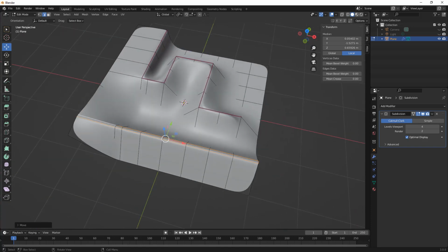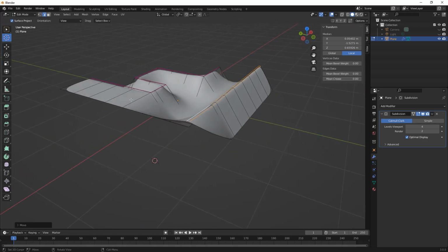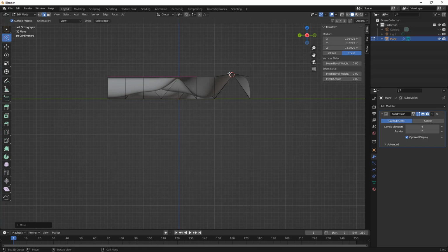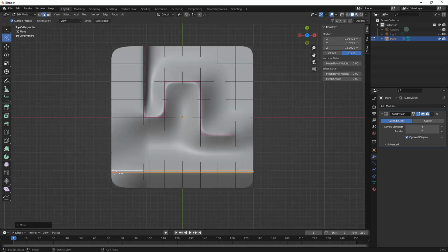But now let's talk about moving that 3D cursor. In order to move the 3D cursor, there are a couple different ways that we can do this. You'll note that there is a cursor menu here, which allows you to set the cursor, and it says drag to transform. So what this allows us to do is simply move it and place it where we want it. There are other ways to do this, and note that this is just simply moving around because we haven't activated any snap yet. So we're just sort of moving it around randomly in 3D. And in order to get it close to right, what we need to do is switch to a couple different views and then just place it in those views.